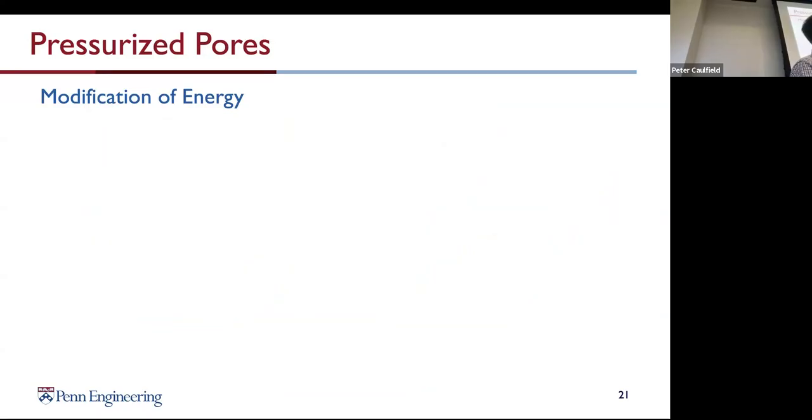In general, this could be a hard problem because you might need to do the whole homogenization procedure from the ground up. So you need to come up with a new estimate for your principal solution. You need to check loss of ellipticity in that solution. You need to do all of these various types of convexifications, check everything, see what happens. But it turns out that because we've modeled the matrix phase behavior as being incompressible, if you look at the finite elasticity boundary value problem that this corresponds to, basically the effect of applying pressure in the pores is the same as the effect of applying tension of that same magnitude on the boundary of the material.